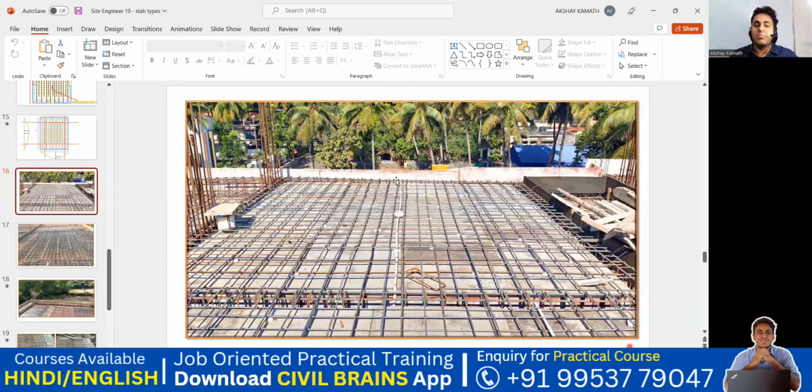So this is a typical beam reinforcement what we get. What we do, we try to provide the crank bar. What a crank bar is has been explained in my construction methodology course. I'll take one bar from here and then I'll do it here. I'll give a crank and take it here. I'll give a crank and take it here. Then again, I brought one more bar, gave crank, took it here, gave crank, took it here. Now I'll take another bar from this side, brought it, gave a crank, took it like this, and then gave a crank, took it like this.